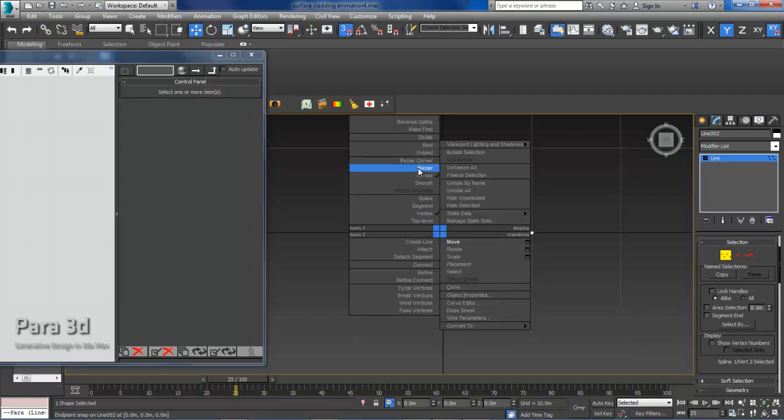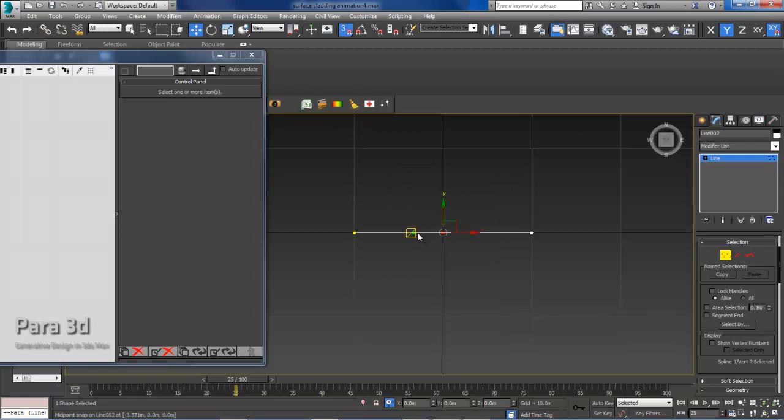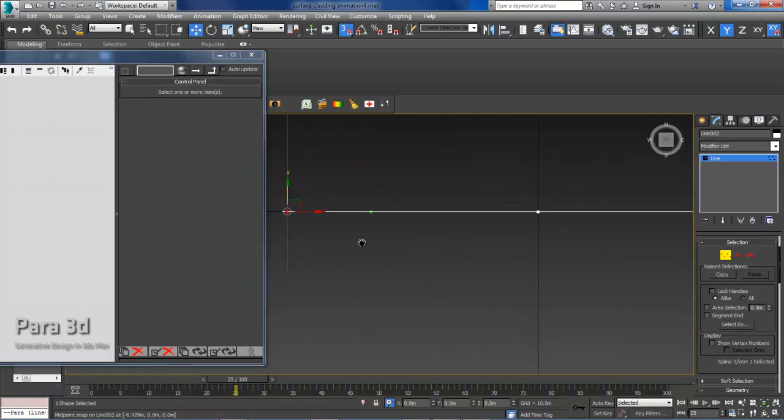this vertex is Bezier vertex, means it has got 2 Bezier handles, and make sure these 2 vertices are Bezier corner, so they also have these handles. As you can see, this little green point, these are the Bezier handles. So you eventually will have 9 control points, because each vertex is going to have 3 control points for each line.